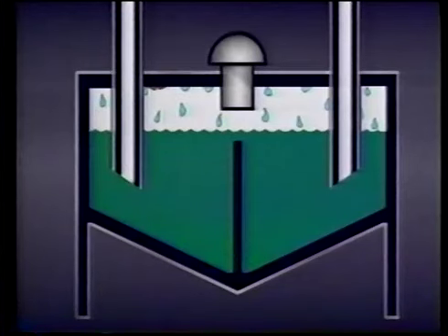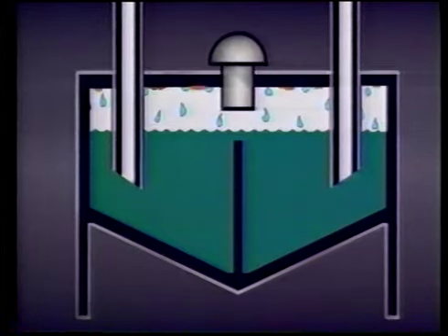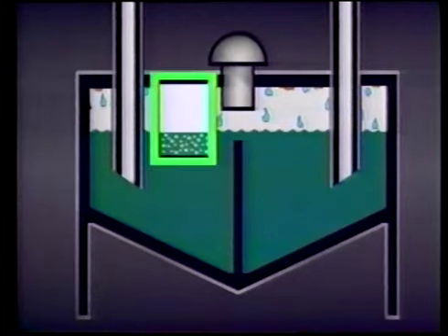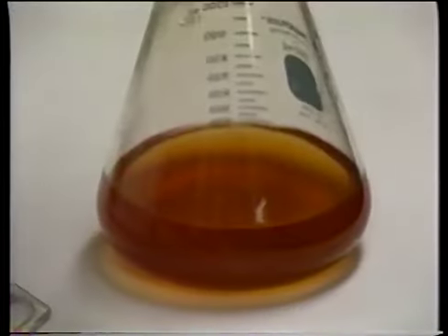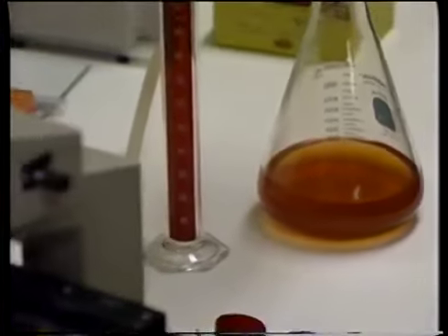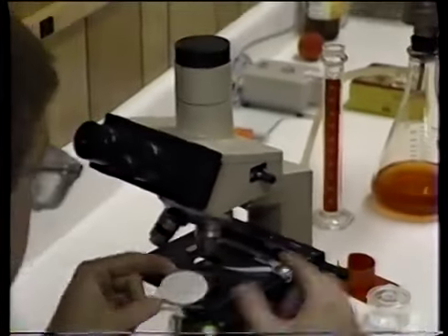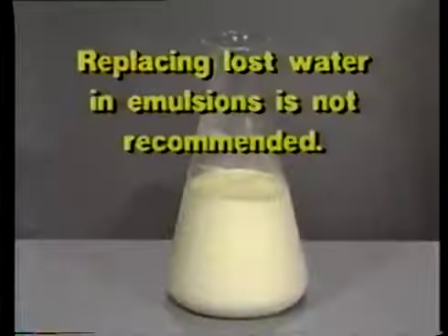Water vapor escaping from the fluid can condense on unprotected metal surfaces, causing rust. Eventually, particles of rust will flake off and contaminate the entire system. Many water-based fluids contain rust inhibitors, but over time, rust will occur anyhow. Evaporation also reduces the fire resistance of the fluid, since less water is available in the fluid. The loss of water also affects the viscosity of a water-based fluid. When using water-based fluids, it's a good idea to have the viscosity checked by a lab periodically to make sure the system is being properly protected.